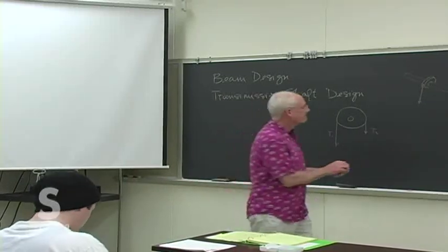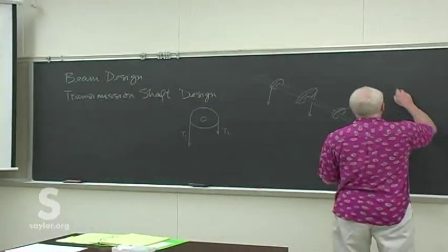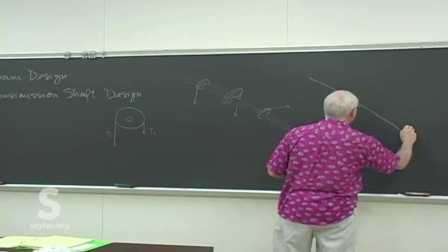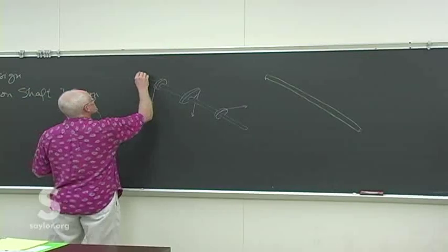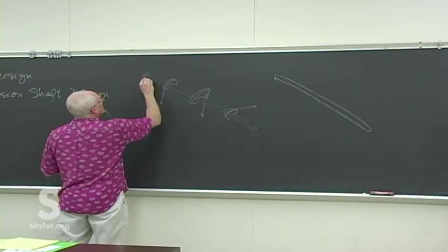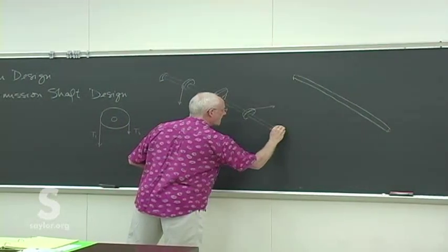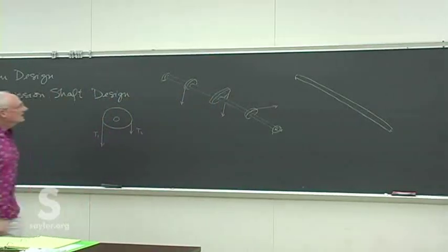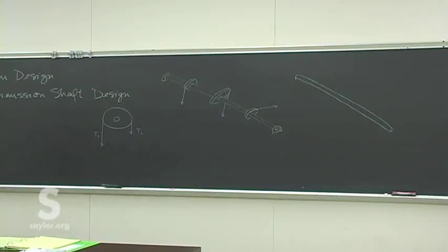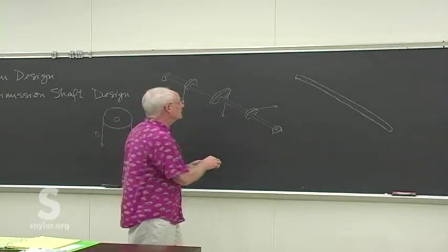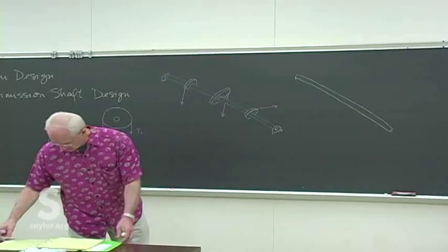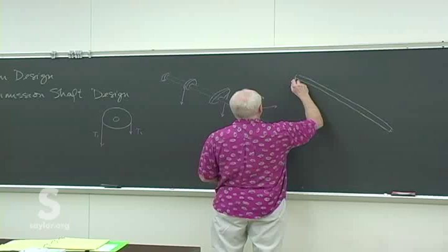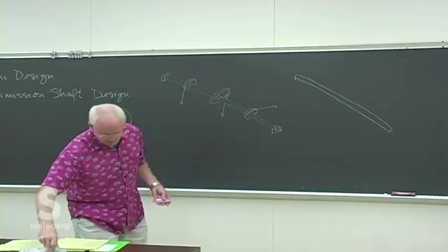So we'll then take this beam, this transmission shaft, and don't forget, of course, there's some kind of bearing that's stabilizing this, allowing it to spin. We assume no torque of any kind applied at those points. Those are just for stabilization. But we need to look at those because there are forces at each of those as well, which are essentially just the reactions.